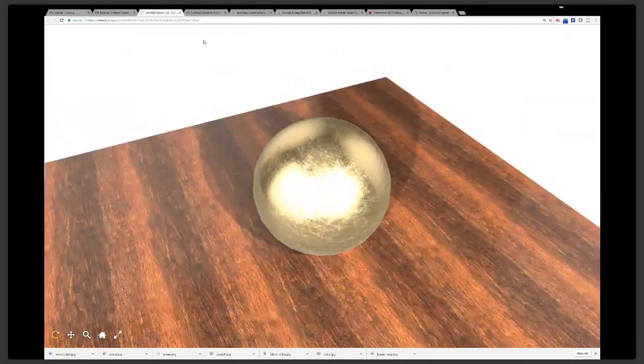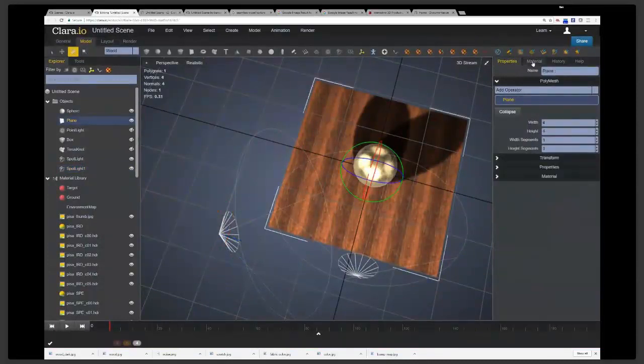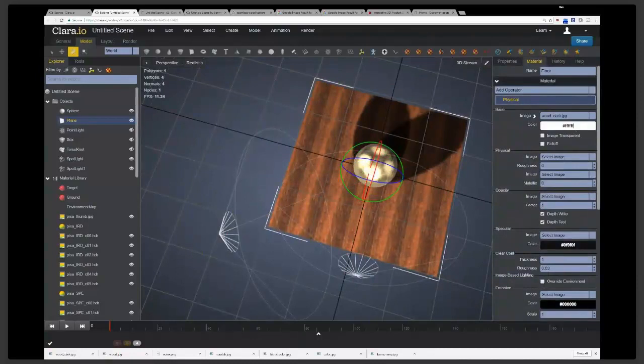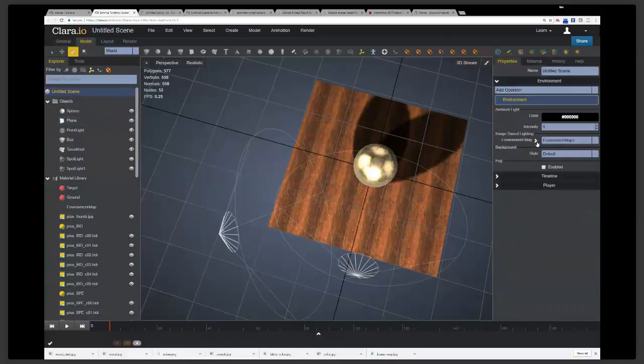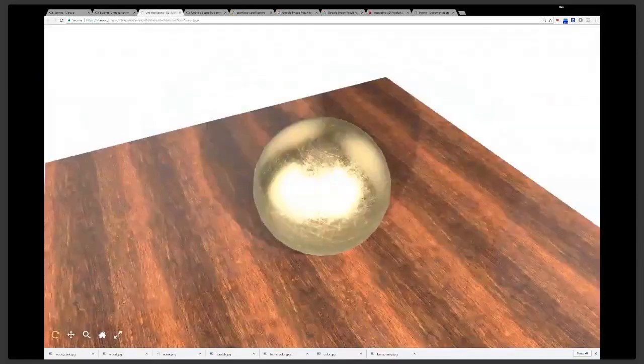I could lower maybe the darkness of the floor, and then it'll be a bit more clear, or it won't be so overwhelming in terms of the bright colors. Or actually, I could lower the intensity of the environment IBL map. Lower that down to, like, say, 3.5, and then it's going to be much more dependent on the lights in the scene.